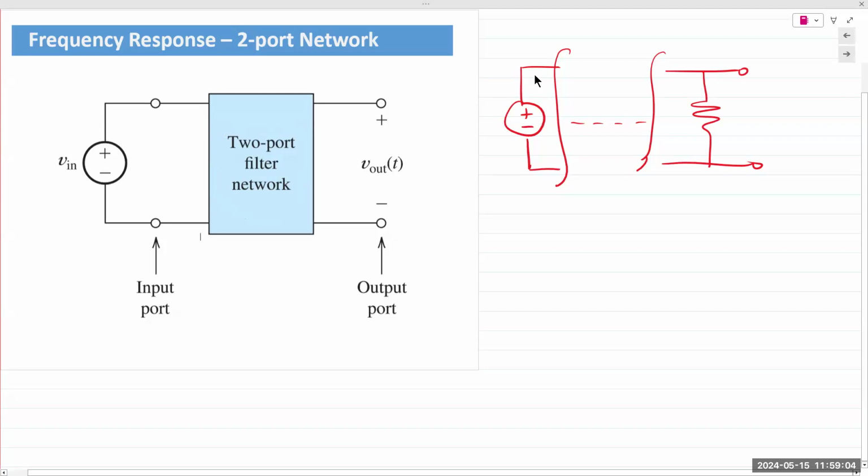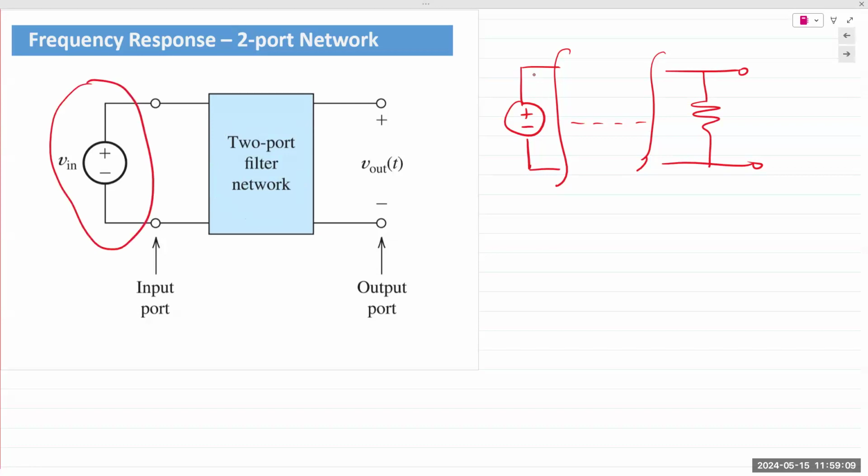by its transfer function. We are going to think in terms of combining the 2 input terminals as a pair of terminals. And it's labeled as a port, P-O-R-T, port. On the left side, typically it's represented from the left side. We say it's being input into the circuit. So we have an input port, and we take the output across a resistor or a capacitor or an inductor, and we tie those terminals together, and we say it's an output port. So we think in terms of input port and output port, where we're taking the output.